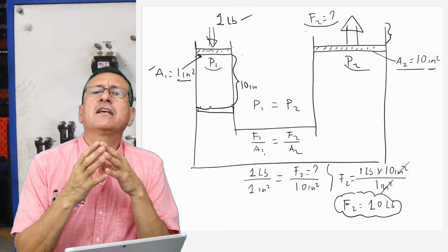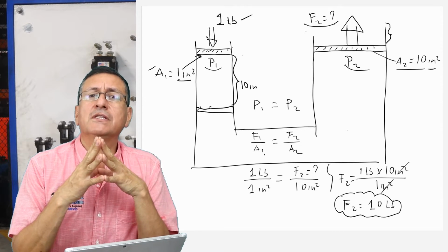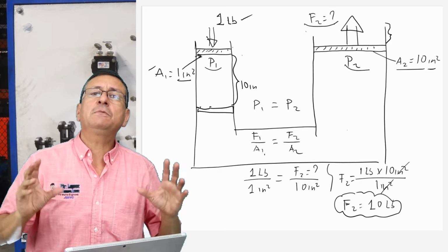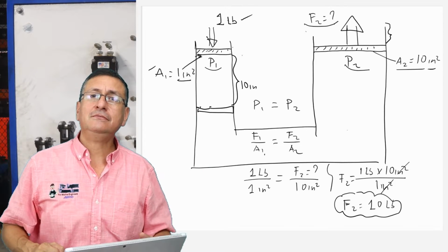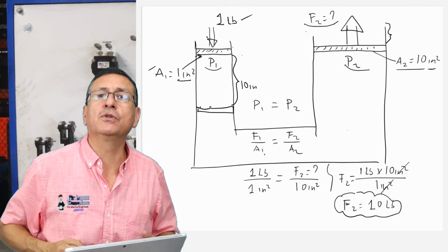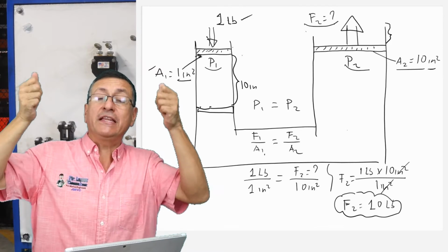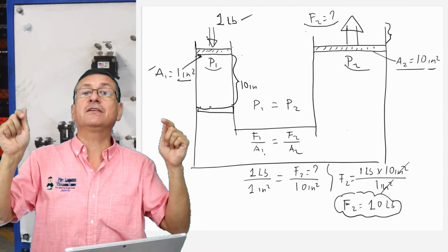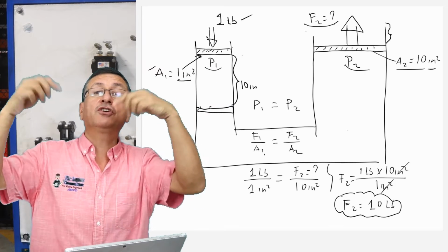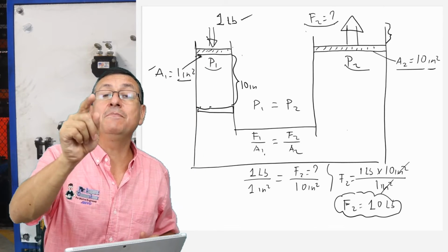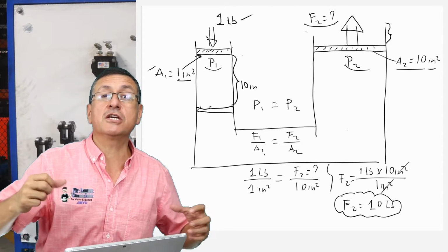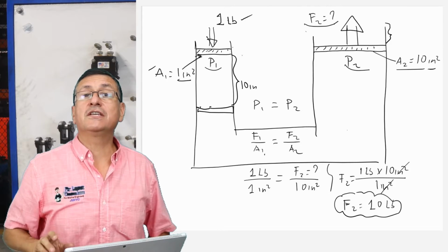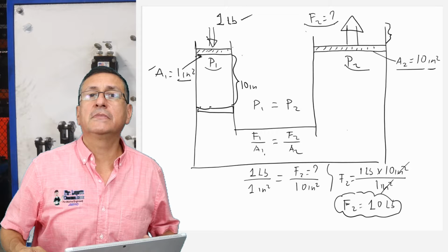Give me examples of hydraulic systems that are not fully closed, not hermetic, partially closed. Yes, the fresh water system in your boat. When you open the faucet for the shower, immediately the pressure in the system reduces because water is coming out at that point. And immediately you hear the fresh water pump start again to pressurize the system. Yes, my friend, the fresh water system is a semi-closed system. It's not fully closed.